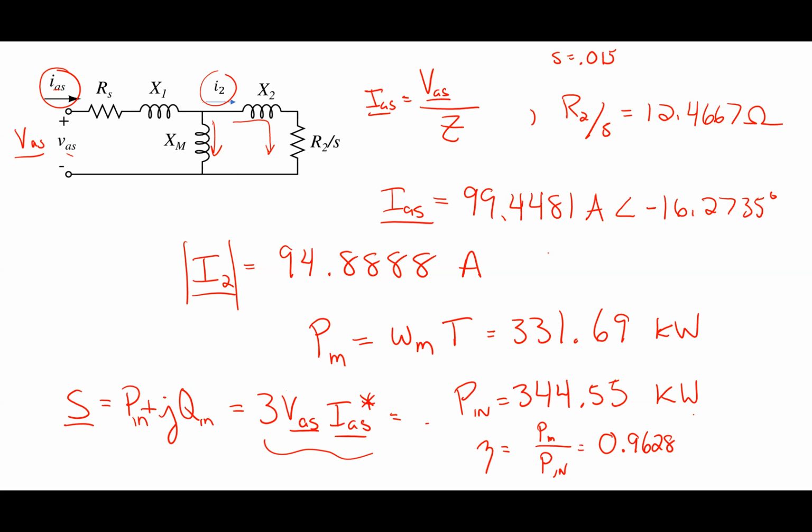Because it only takes... so the motor, yeah, good question. The fan motor, let's say in your air conditioner, is probably 1/6 horsepower, right? I don't feel uncomfortable grabbing the shaft of that thing and not having it hurt me. It's just a weenie motor. So at low power levels, it's just not worth the cost to make an efficient motor, right? That's really what it comes down to.